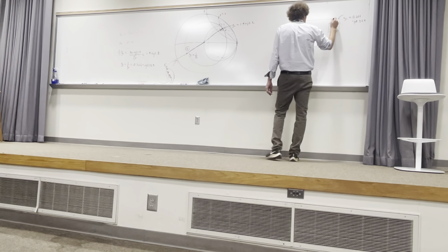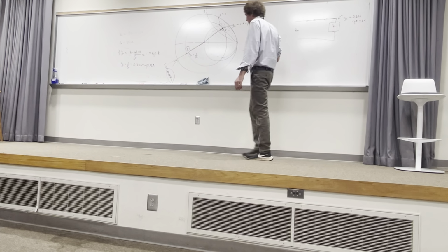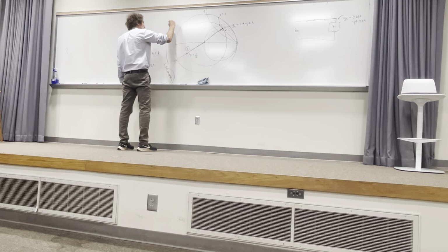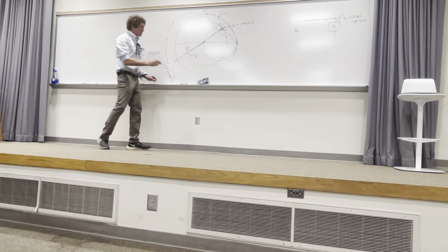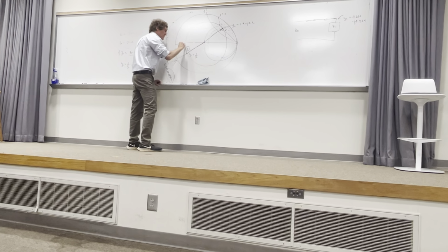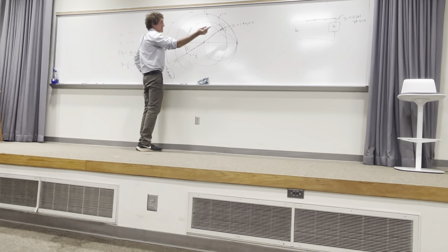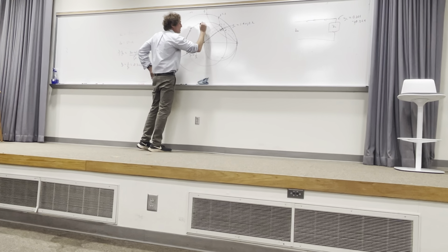Now I'm going to start moving this way for an attachment point. As I'm moving that way, on this circle, I'm moving wavelengths towards generator. I'm going to be moving on this inner circle. This is actually the possible values for the input admittance as I move closer or further away from the load.